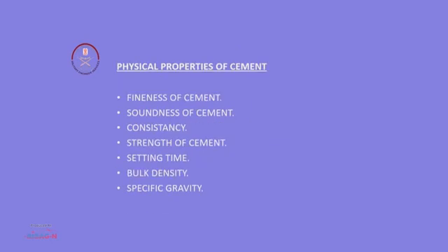Here I have listed some physical properties of cement: fineness, soundness, consistency, strength, setting time, bulk density, and specific gravity. If we speak about fineness, fineness is very important for the hydration process. If fineness is not as per the standard, hydration will not take place as per the specification and it will not result in enough strength. This is one of the important characteristics.